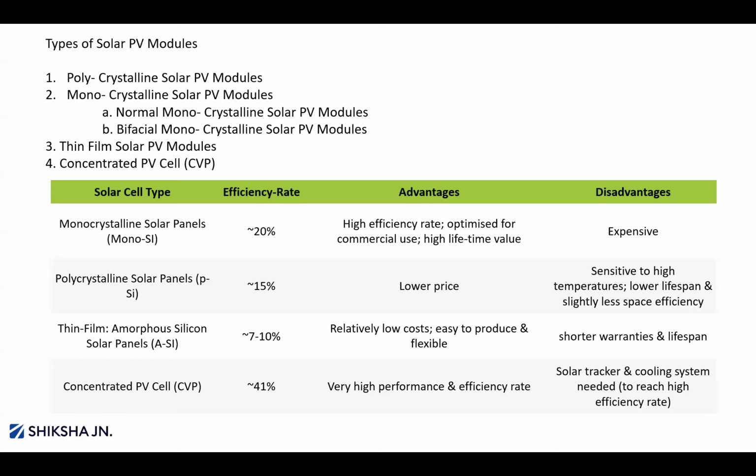In that, two types are there: monofacial or bifacial. Both are being used, and a lot of people use bifacial also. Compared to monofacial, with bifacial modules we can get almost 5 to 10% extra energy, because the backside is transparent, so we can get generation from the backside also. That is what bifacial means.